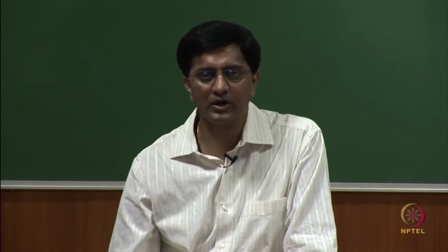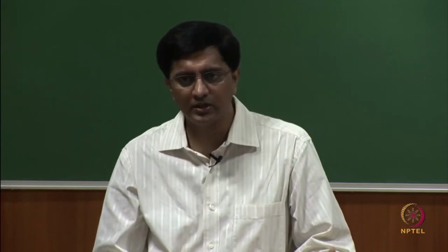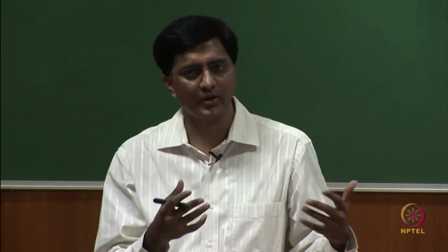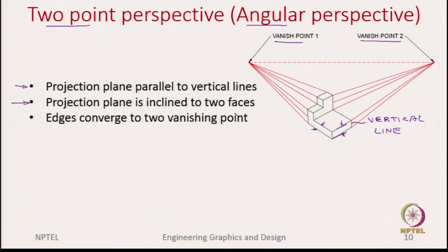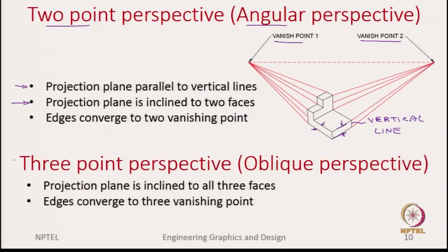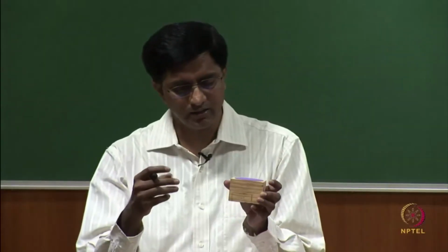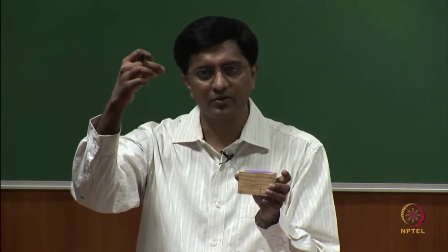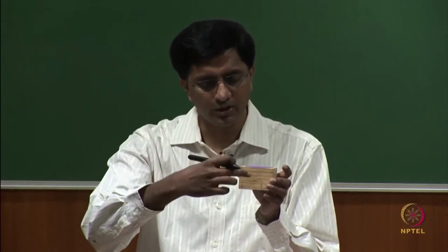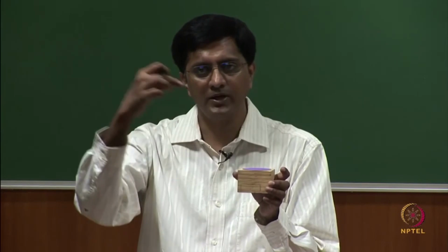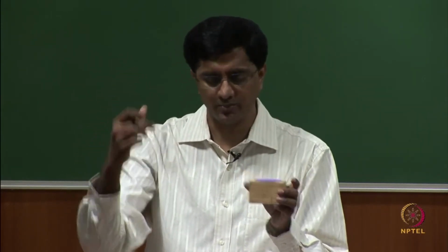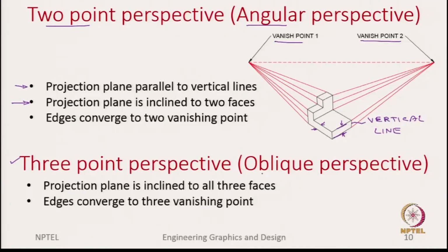Usually most of them are 2 point perspective, because it gives you an impression that you are standing next to the building and looking at it. Okay. And lastly, the 3 point perspective. Here, as we said in that example, we now take a drone and look at the same building from the top, such that we see the front, side and top of the building. Then we capture the 3 point perspective, also called the oblique perspective.